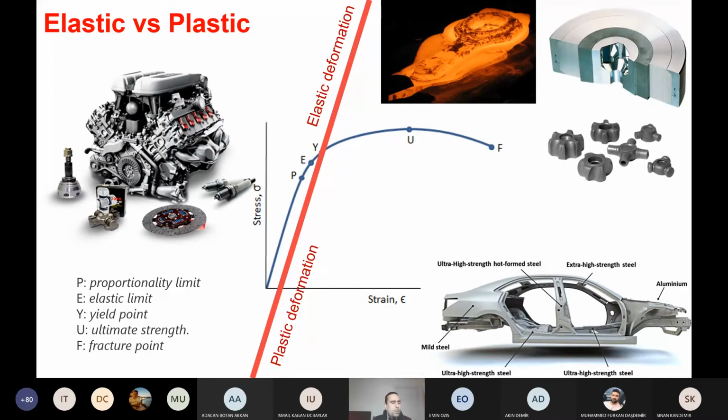I will name two different words that we also often use in numerical simulation. It is linear analysis and non-linear analysis. When you talk about the elastic deformation, if we just ignore these two small sections, the non-linear curved part, elastic deformation for metals is assumed to be completely linear. So that is why in a CAD software, it's quite easy to perform a simulation of a body like a connecting rod. You just fix and you apply some forces, and in 10 seconds, you get a result, some nice colorful pictures showing the deformations and stresses. However,